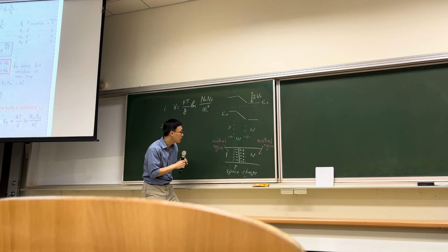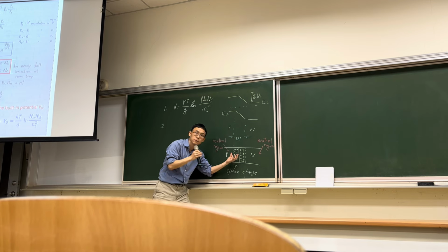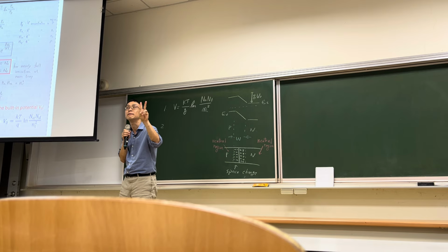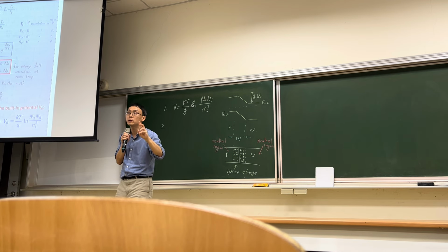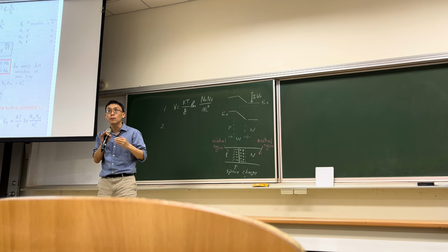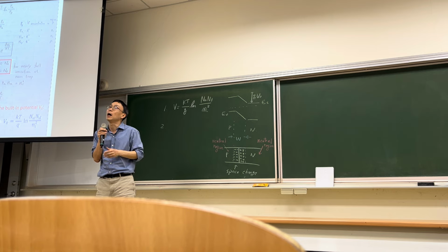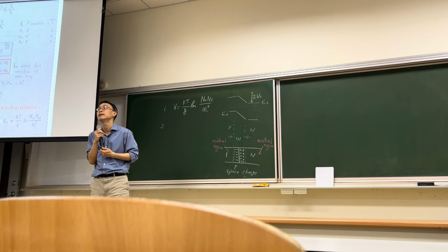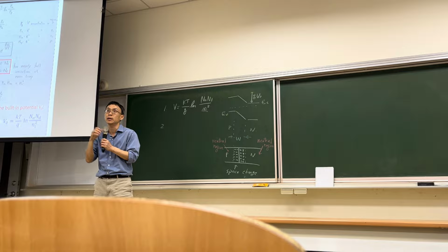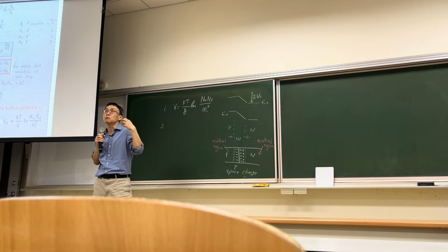Right, so we know this width of the space charge region is very important for two kinds of devices. Because this region is the active region that can produce usable currents for the solar cell and the photodetector. Because the solar cell and the photodetector are producing electrical currents by photons.